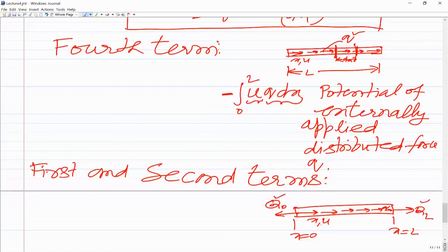Another thing is you would have studied the sign convention for stresses and these internal forces. Now if you look at this right side, the outward normal to the cross section is along the positive x direction. So QL is taken positive along the positive coordinate direction on a positive face. Positive face means the outward normal is along the positive coordinate direction.